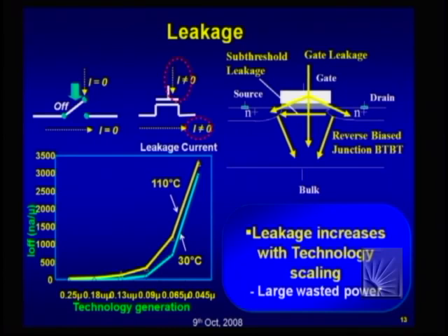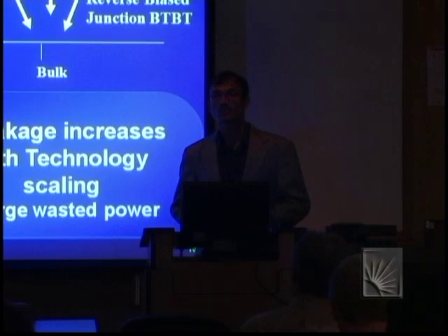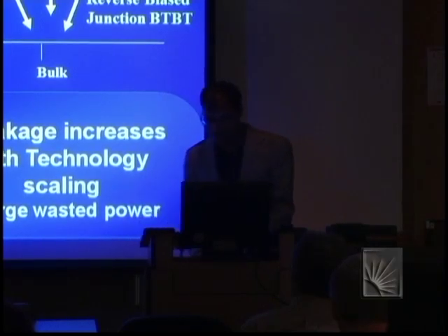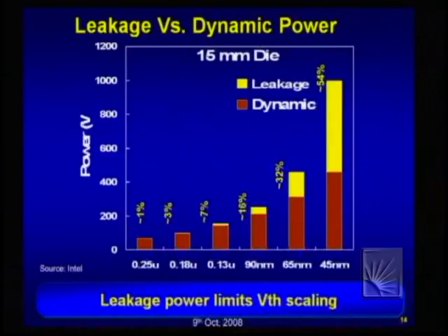If it is increasing exponentially, then the leakage current is becoming more and more important in nanoscale devices. And I talked to Intel very recently, and unofficial information from them is that right now for the processors the total leakage power is 50% of the overall power. So, that is a lot, and you cannot probably tolerate that much power.